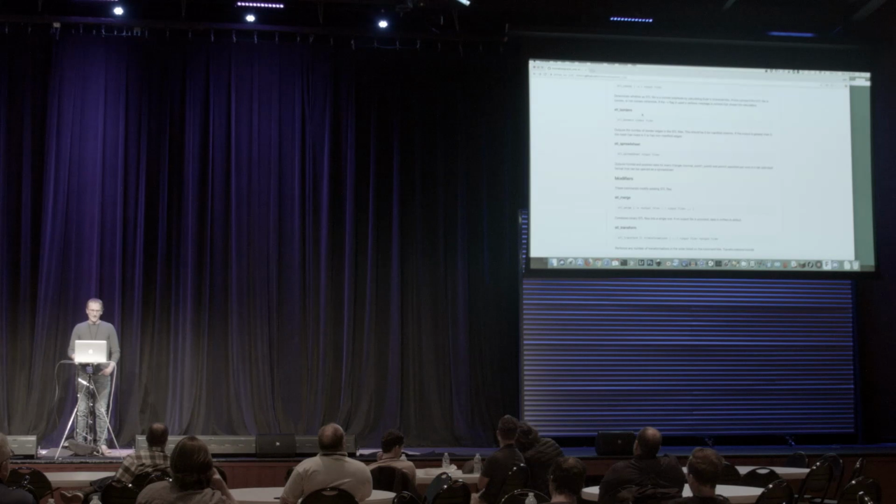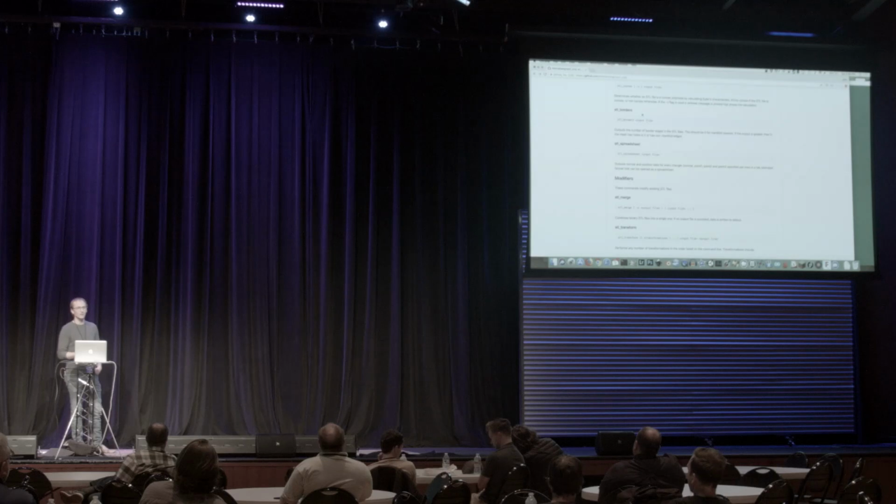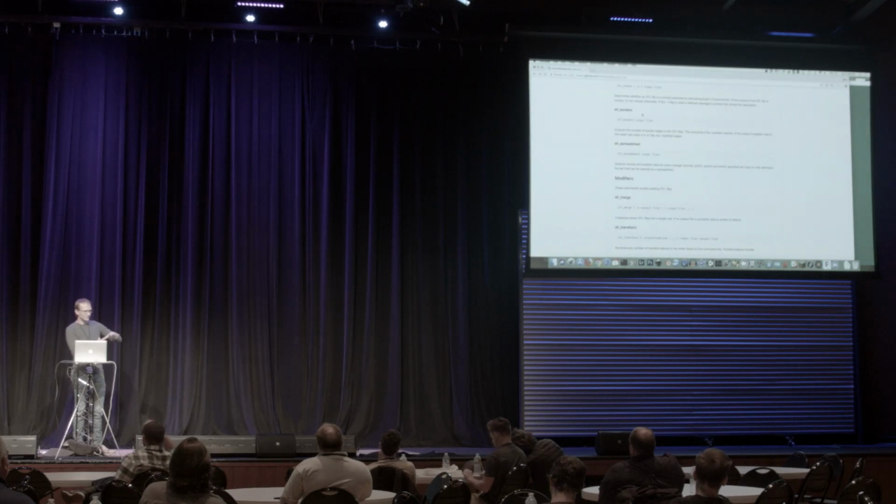STL borders. So when you're 3D printing, you want it to be a manifold watertight model. And that just means that the surface of your 3D model is completely contained. Like this is made up of triangles, which are an infinitely thin thing. So you need to have an inside of your model and an outside. And so when there's a hole, if you have a triangle missing, you'll have border edges that don't have a pair. So like if you have 2 triangles next to each other, you'll have 2 edges, and that's not a border edge.